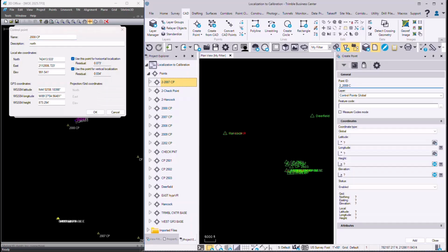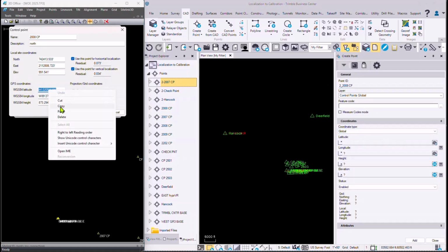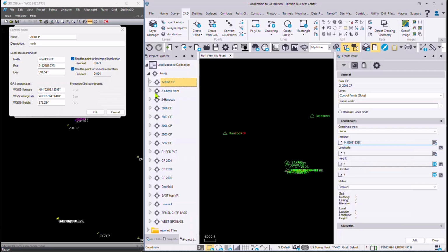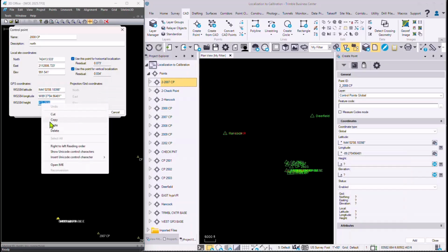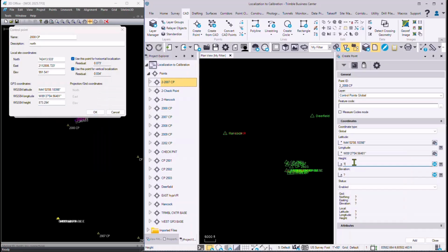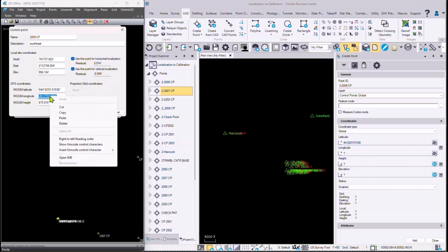so that I can verify the global control points all match. When you get in a rhythm of copying and pasting these numbers, it might take you 30 seconds a control point, and if there are a dozen control points you have to create, that's 6 minutes. 6 minutes to verify the coordinates match is not that long of time. You see, it goes along quickly. We're wrapping up with the last control point. It doesn't take that long to create the global control points.